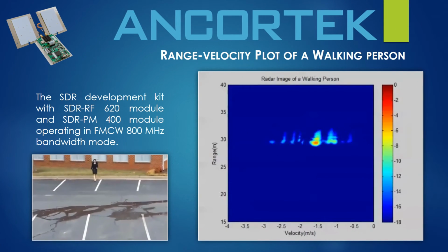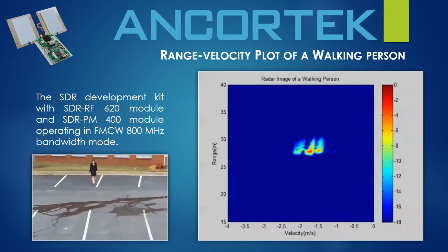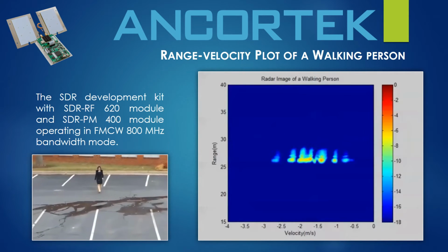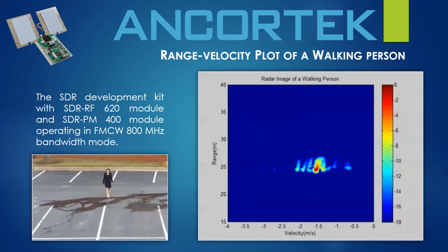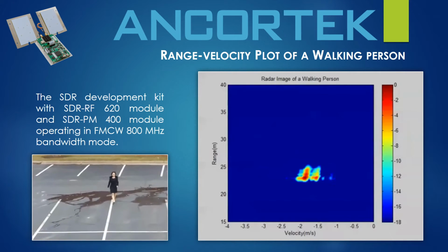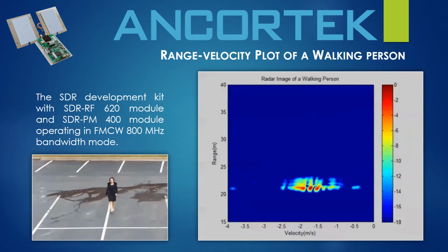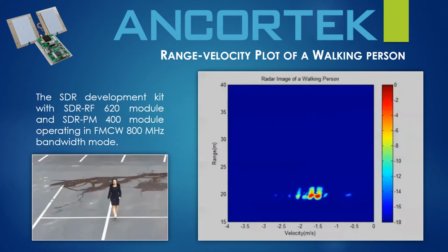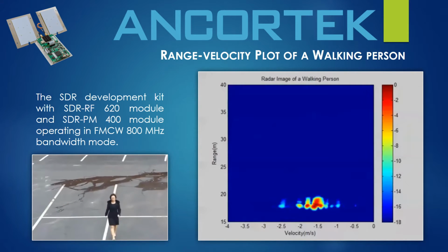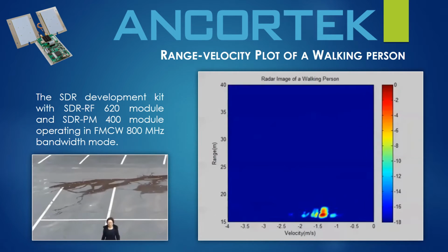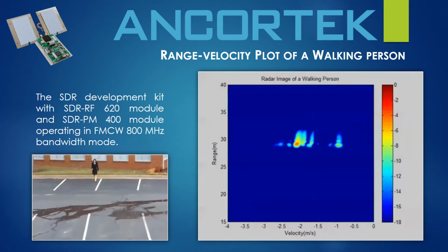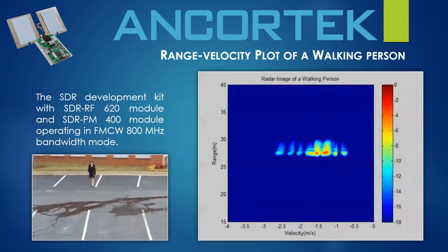In this scene, we've taken the raw output of the radar and created a short movie clip of the range Doppler map over time. You can observe that as our pedestrian switches from her left foot to her right, she will pause and the observed side lobes decay. As she proceeds to move forward, the return from her forward-moving leg is caught by the radar and is displayed as a faster object than her torso.